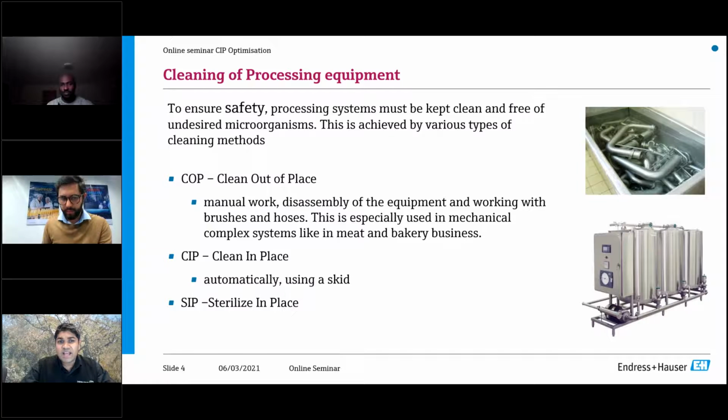The most common practice that I've noticed is the CIP. This is cleaning in place, whereby there's no mechanical activity done in terms of removing piping from the line. Basically, the process is cleaned using chemicals. Normally this is done with a rinsing of the line, then an alkali solution is pumped through the process for a period of time. It's then rinsed again, and then the line is considered to be clean. Normally these come in typical skid fashion from skid builders, so a quite compact automated unit.